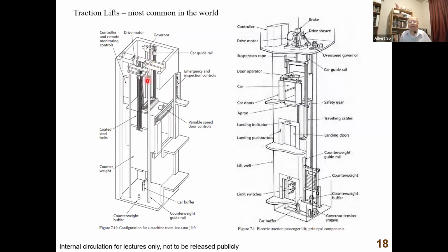So since there's nothing below the platform, if there's something wrong with the platform, you fall down. So that's why it's not very safe. But if you work inside a machine room, it's safe. It's a room, okay, safe. More difficult to repair the gear, but of course there are a lot of requirements on the maintenance platform for machine roomless.